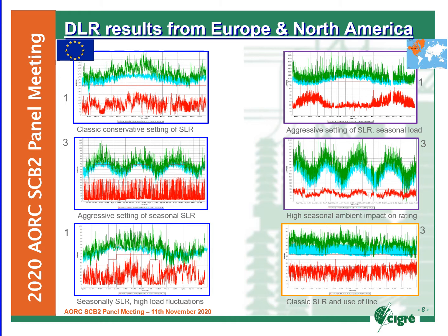Usually, the static line rating is set to a value that allows 2% of the risk of the ambient adjusted rating. That means that the blue curve may go below the static rating 2% of the time. Typically, this would mean values like 40 degrees in summer and 20 degrees Celsius in winter. There's a chance that such temperatures would be exceeded, but not very often.